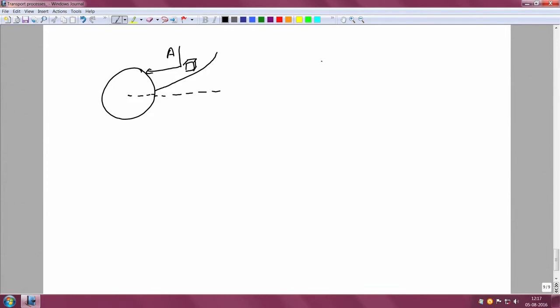Similarly, for the pipe flow, I will try to get the entire velocity as a function of distance from the wall. Once I have that solution for the velocity everywhere, I can find the shear stress at the surface from Newton's law of viscosity, and from that I will know the wall shear stress, and therefore the pressure difference that has to be applied.